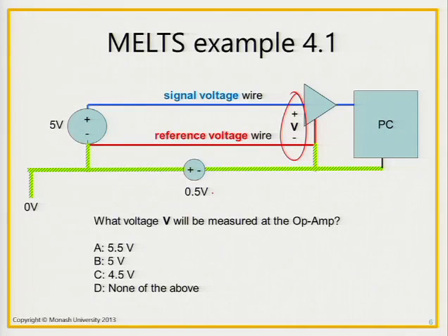If you're still not clear where this comes from, it comes because you have currents that could flow through here. Sometimes these currents are really, really large because they might be powering, say, a really big motor that draws a lot of current. And because this wire has some resistance, this V here would be equal to IR. That's where that voltage drop comes from.